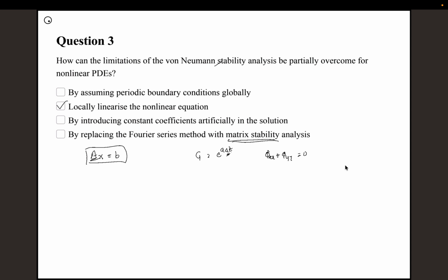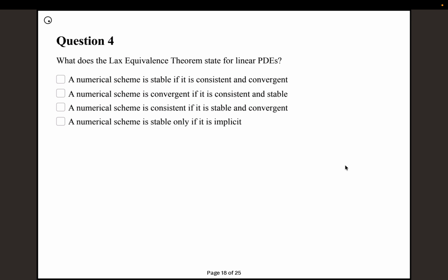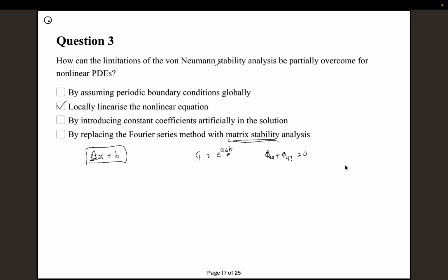In order to understand that, you have to understand this matrix A that you populated, through something called the condition number, which will decide whether you'll actually get a solution or not. This is not covered in this particular week, but we can take it up next week. Or if you're interested, you can look up how to estimate the condition number of this matrix and how that affects the convergence of your solution for elliptic equations.